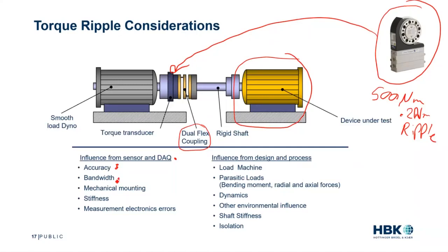Our sensors currently offer 6 kilohertz of bandwidth. We're looking at some ways to improve that in the next generation. But you really need to consider what's the bandwidth of my measurement. And if you already have a torque sensor, you need to start thinking about, all right, my T12 HP has some internal filter settings.